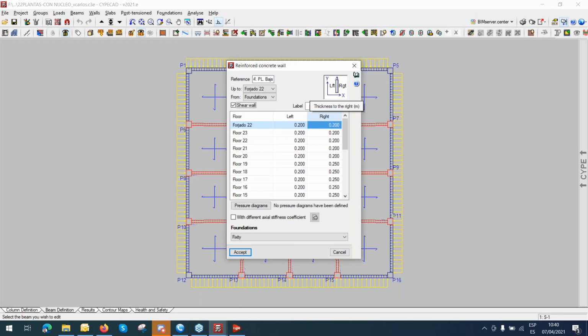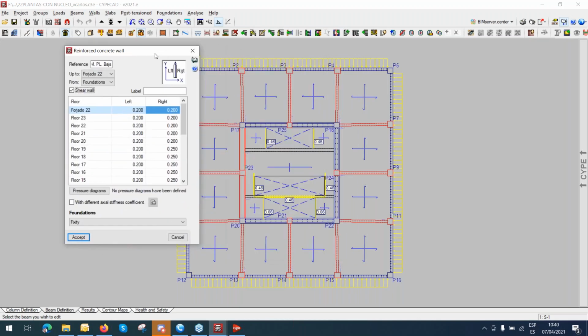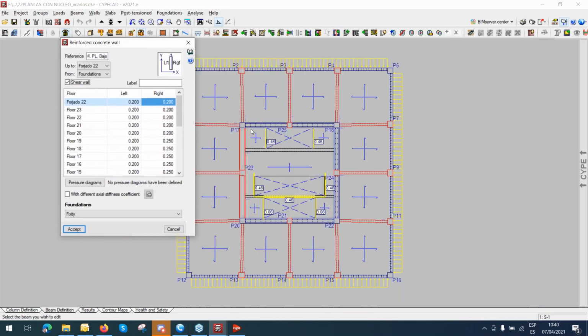And with that software, it's possible to be sure that in these segments of wall, the software is going to analyze if it's possible to introduce an extra reinforcement. Right now we are using columns, but with the shear wall design, the edge elements are going to be there because the software already introduced the effort coming from CYPECAD and you use it in the software. So you will be able to find this information right there, and you can also get plans and drawings and